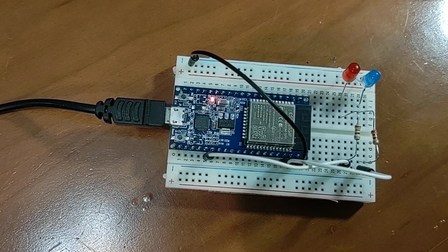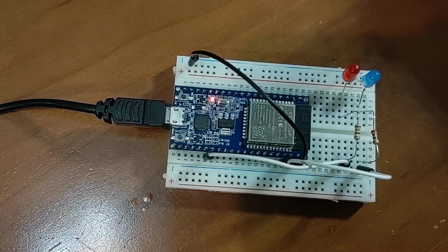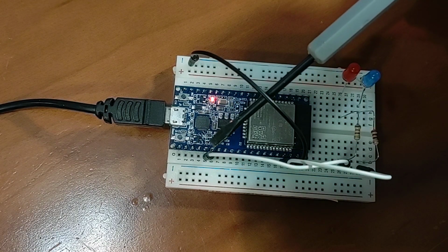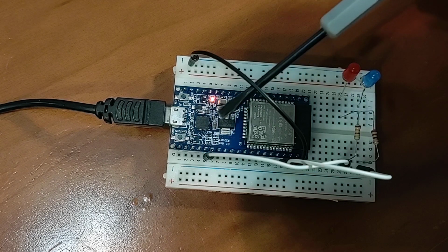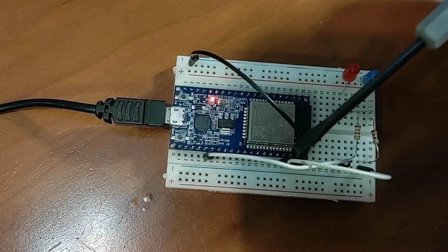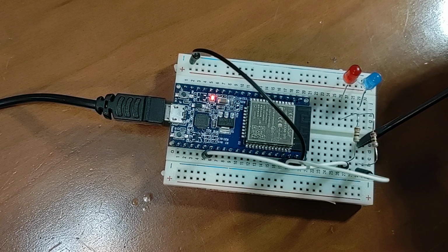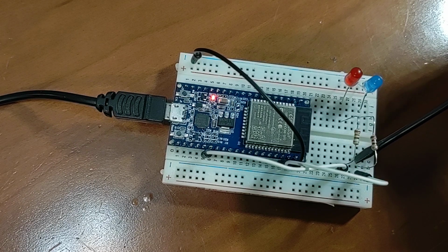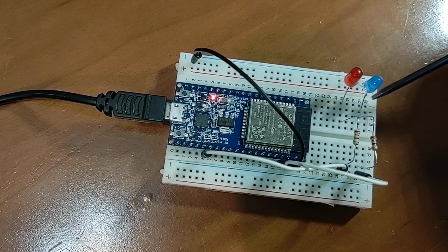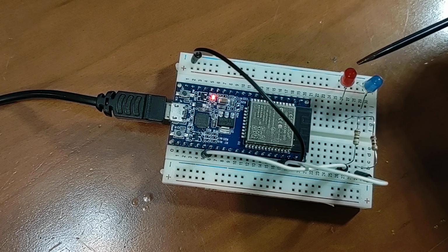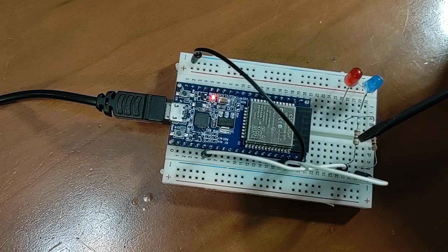So what I've got here now is the ESP32, and you can see that I've got a white wire coming from pins 2 and 22 going over to these two rows over here. Each of these rows that go this way are all connected together. There's an open space in the middle, and then each of the rows on this side are also connected. So the output of this resistor is connected to the input, or the anode, of this blue LED, and the same for this red LED, except with this resistor over here.